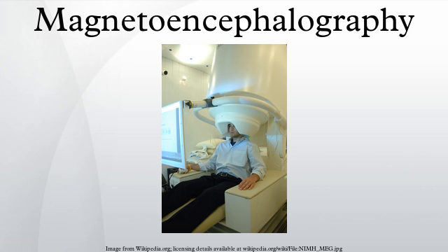The extent to which the constraint-free MEG inverse problem is ill-posed cannot be overemphasized. If one's goal is to estimate the current density within the human brain with say a 5 mm resolution, then it is well established that the vast majority of the information needed to perform a unique inversion must come not from the magnetic field measurement but rather from the constraints applied to the problem. Furthermore, even when a unique inversion is possible in the presence of such constraints, said inversion can be unstable. These conclusions are easily deduced from published works.